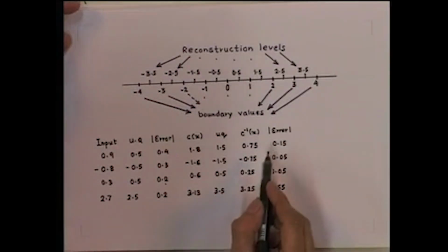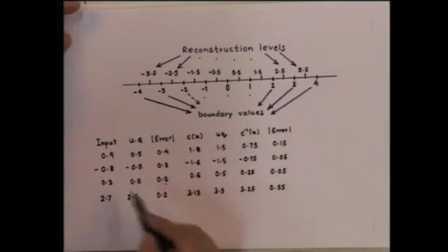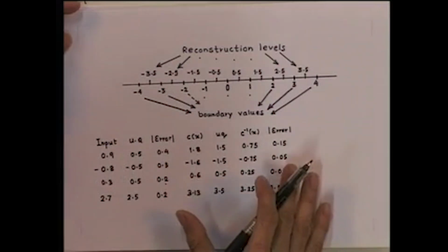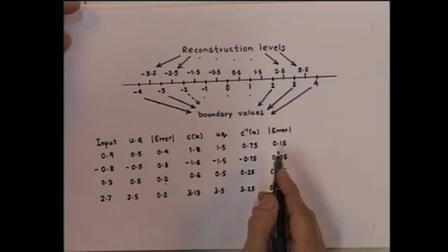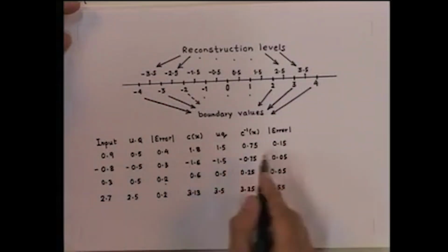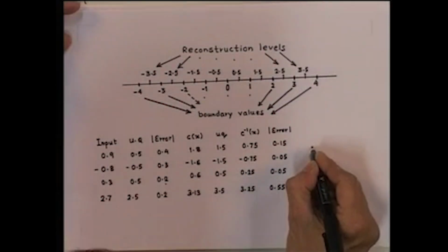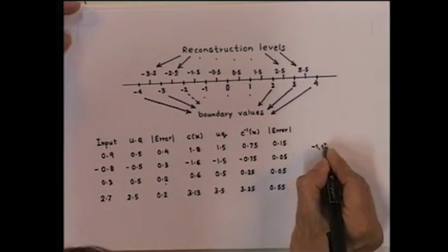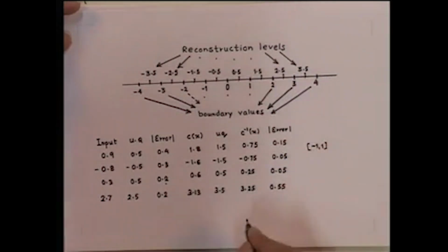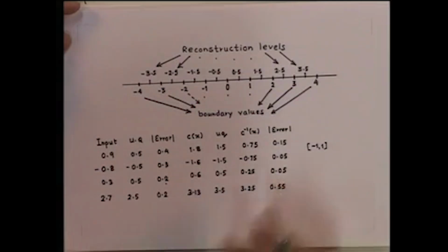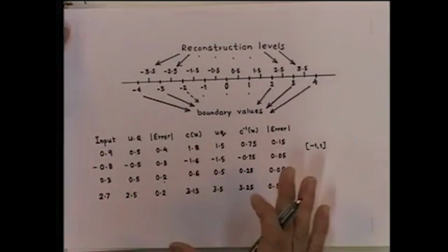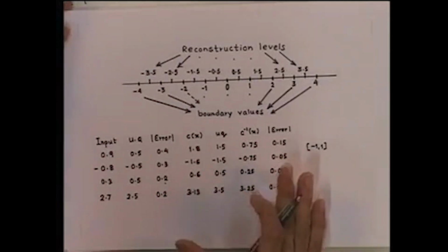So, the companded quantizer effectively works like a non-uniform quantizer with small quantization intervals in the interval between -1 to +1 and larger quantization intervals outside this interval. So, the next question is, what is the effective input output mapping for this quantizer?